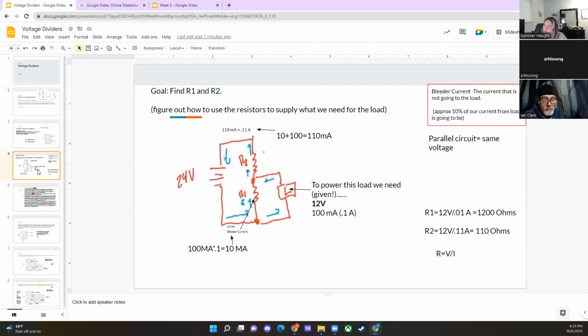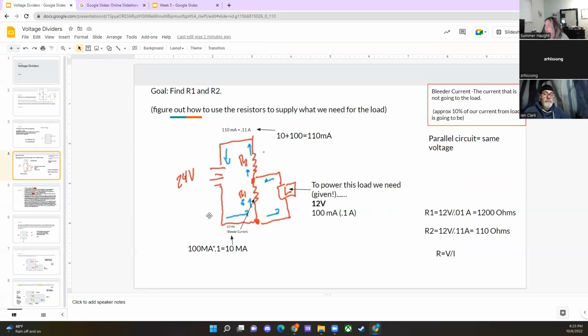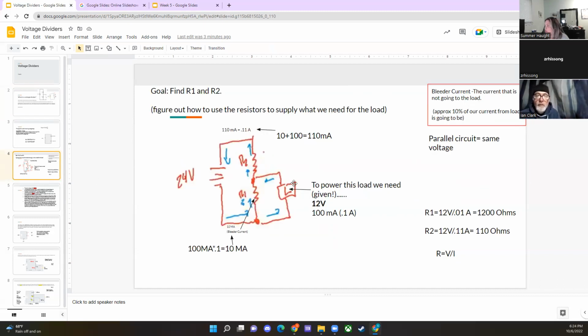Okay, so one of the first videos they do, and the videos can be a little bit confusing, so I normally like to screenshot it and walk through it again. In this video, you can see that this looks exactly like that voltage divider situation. We had one resistor parallel to that V out and one outside of it, which is exactly what this looks like. Typically, this V out means we have some sort of load there that we're trying to wire. In the examples they do, it's usually just a light bulb, since that's the most generic load we see. It's something we want to give power to.